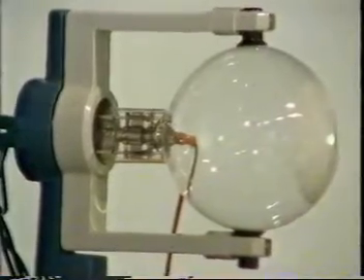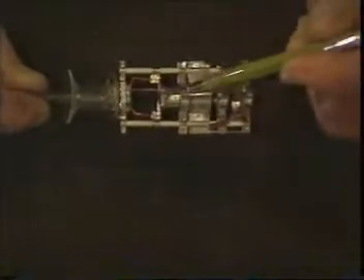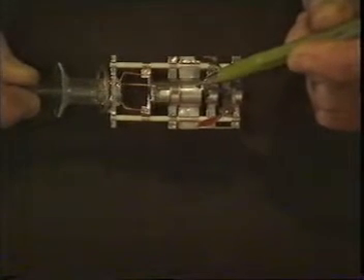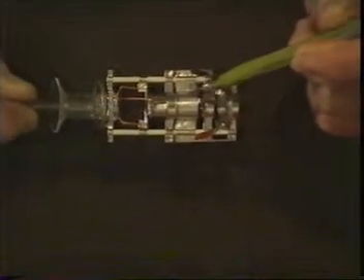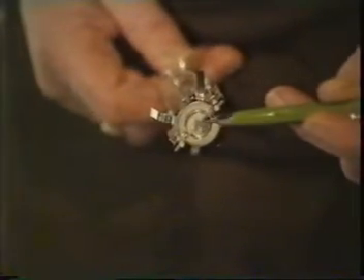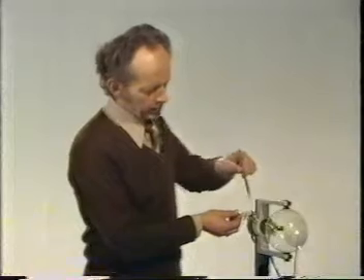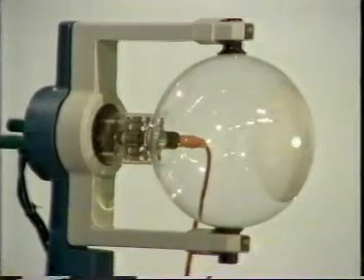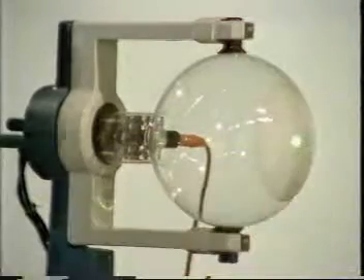I can show this best with this duplicate set here. This is the heated cathode, and that emits the electrons. This is a plate which can be charged up to a high voltage, several thousand volts. And that means that the electrons get accelerated from the cathode along here, and they come out of that hole at the end there. They come out in the form of a fine pencil beam. And they go shooting across this evacuated tube. And the reason it's evacuated is that we want to cut down the collisions with the air molecules. And then the electrons strike this fluorescent screen and give rise to this spot.